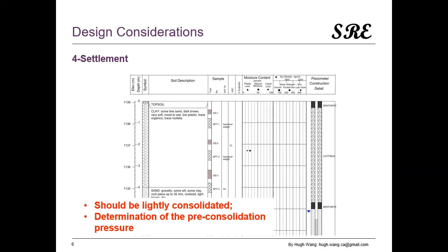The third aspect is about settlement. No matter if it's a foundation or embankment or other structures, when we do the settlement calculation, a very important thing is to first identify whether this clay is normally consolidated or overconsolidated. As we mentioned before, the clay should be lightly overconsolidated.